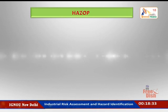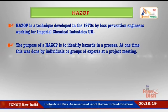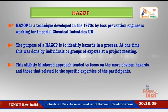So next is HAZOP. So, hazard and operability studies. So what does it mean? It is a technique which was developed in the 1970s by loss prevention engineers working for the Imperial Chemical Industries in the UK. So this procedure is to identify hazards in a process. So that means at one time this was done by individuals or groups of experts at the project meeting. So this approach tended to focus on the more obvious hazards, and those related to the specific expertise